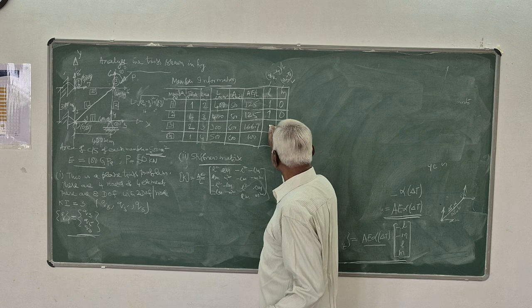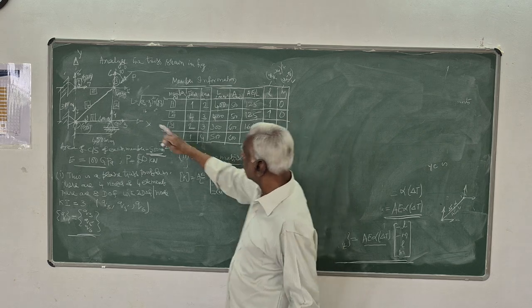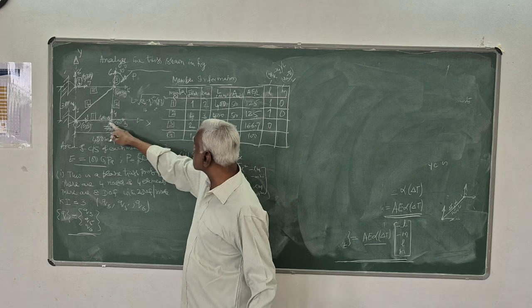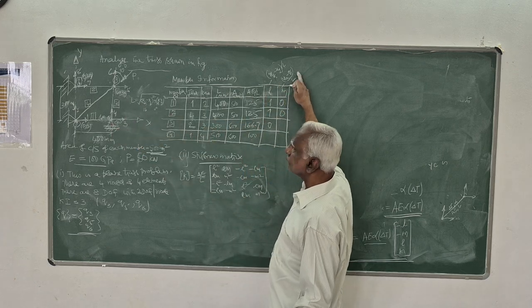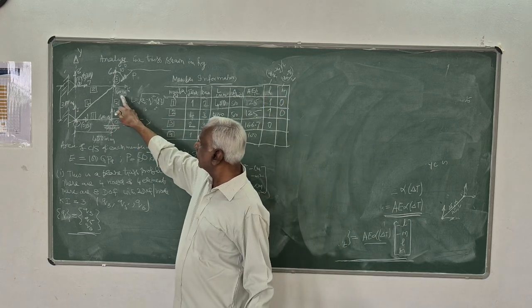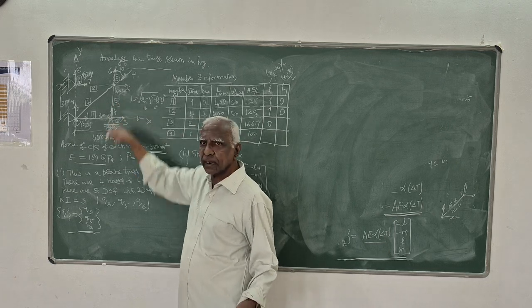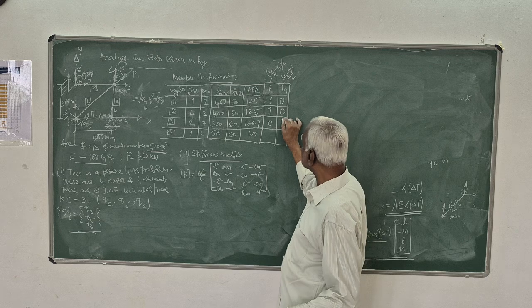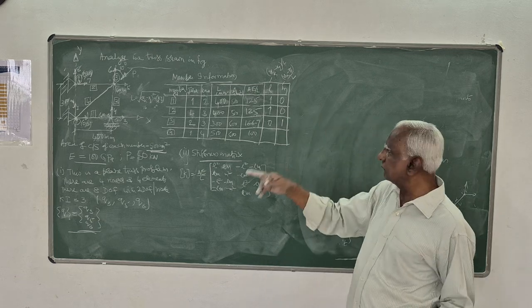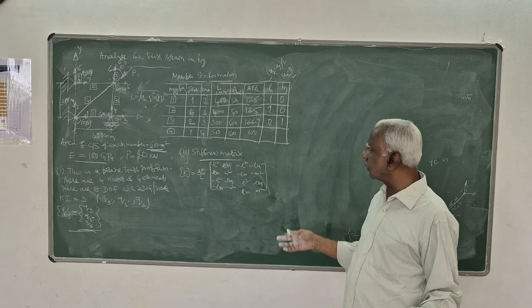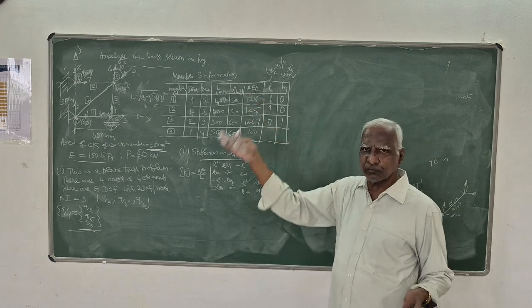So here this is 0 and this is y3 minus y2. y3, that is 300 minus 0, 300 divided by 300. This is 1. For vertical member, it is 0, 1. Horizontal member, 1, 0. For inclined member, you have to work out.